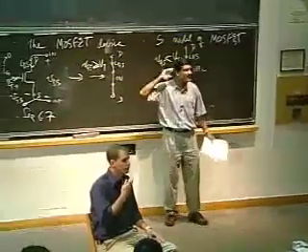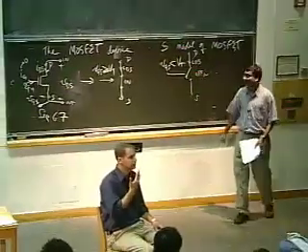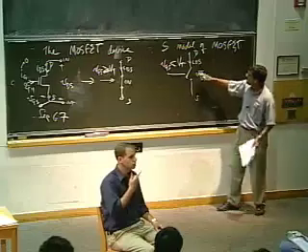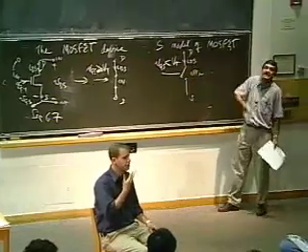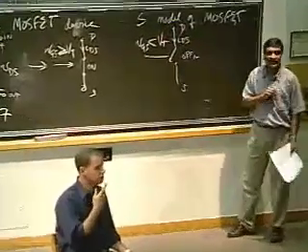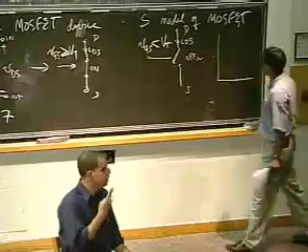Just like my switch, just when in doubt, think faucet. When you put pressure on the faucet, think of this as closing, and when I open it, when VGS goes less than VT, less than a threshold, I take off the pressure, then it becomes an open circuit. So I can plot the following.